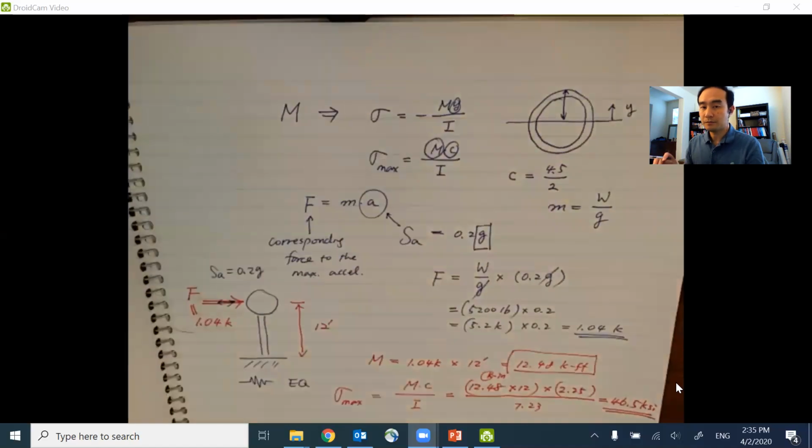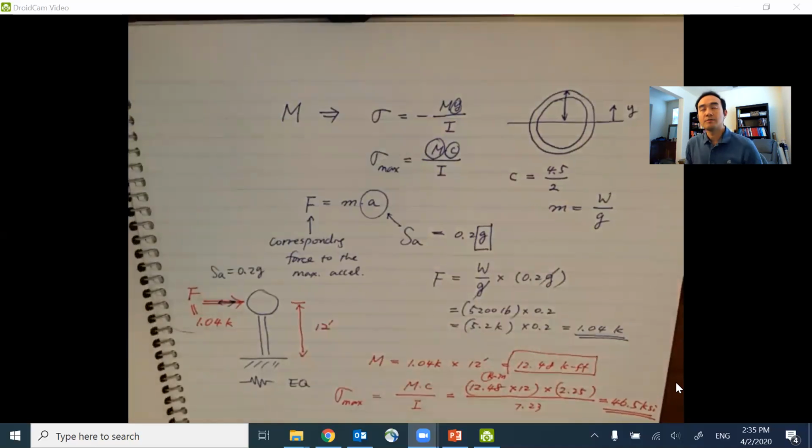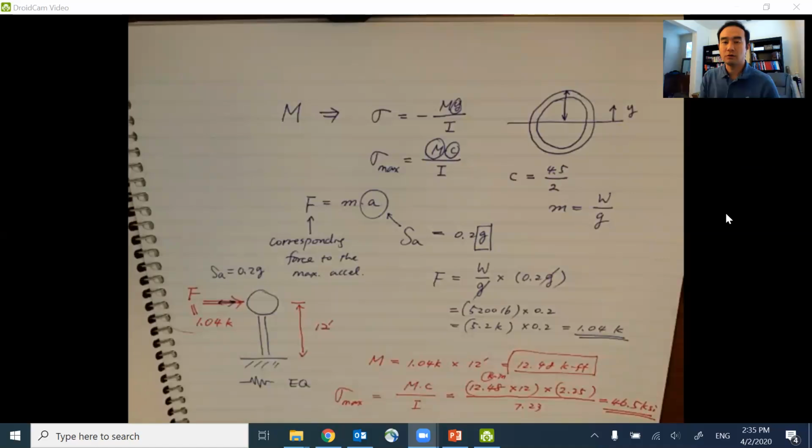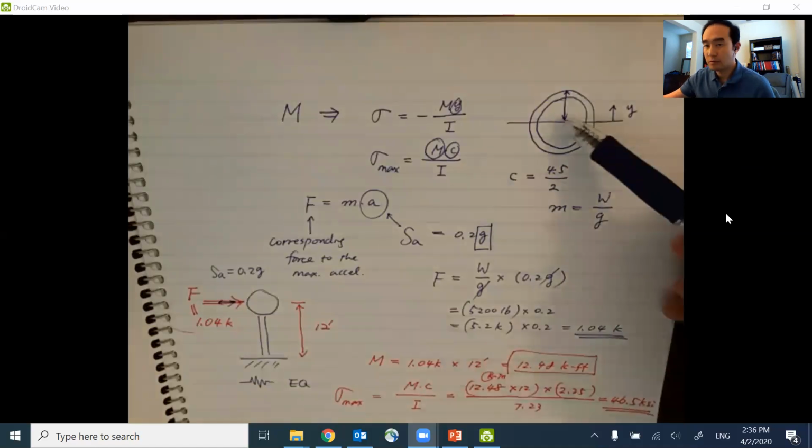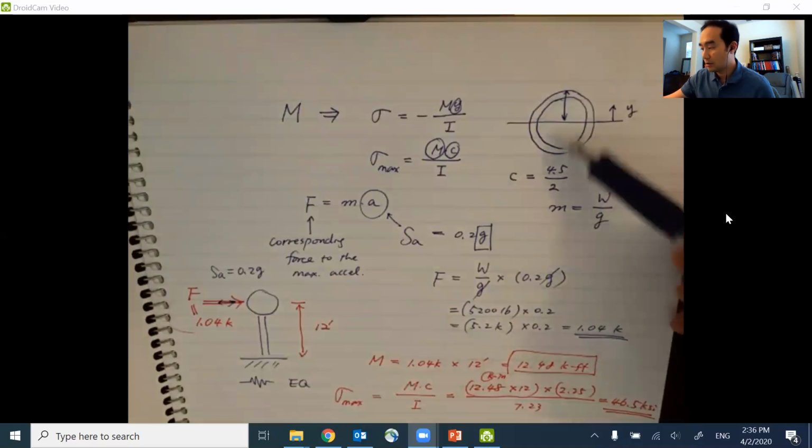And then the first question was what was the maximum peak deformation. Directly using the response spectrum, we got 5 inches of displacement. And the second part of the question was the maximum bending stress. Using the sigma equation, sigma is equal to Mc over I, and c is the maximum y value, which is half of the outer diameter.